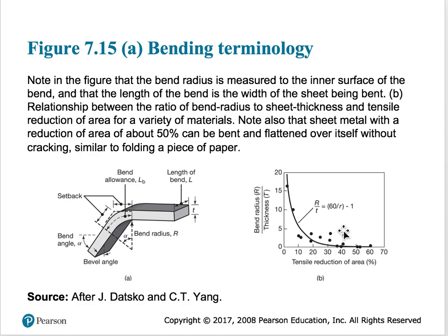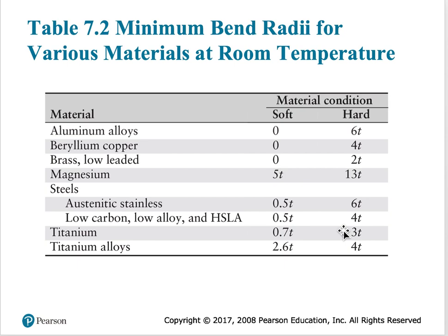Now, one thing to note is that when you bend something, there is going to be some kind of distortion. The outer and inner strains are different, and that difference will increase with the ratio of the radius over thickness. So the higher the thickness, the more the distortion. Okay. There are some equations here. Please take a look at that.